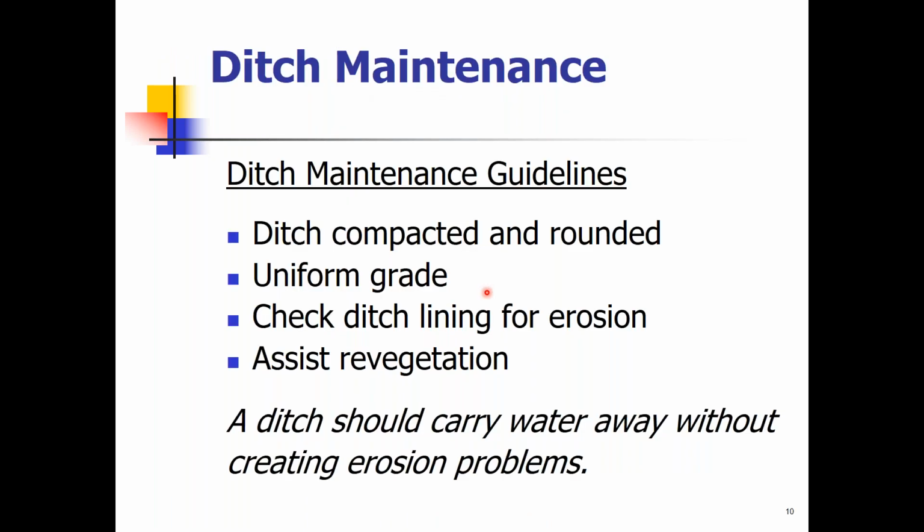In terms of ditch maintenance, please make your ditch compacted and rounded. And we'll talk about compaction towards the end of this presentation. Make sure the grade is the same on both sides. You don't want different grades going down that roadway. It creates a hazard, number one. Number two, it can also lead to liability if there's an issue.